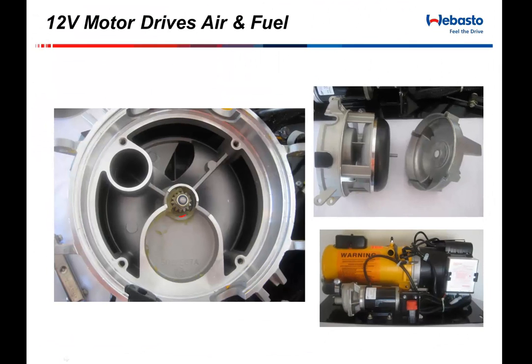On the other end of that shaft is this gear, which again is driving the fuel pump. So it's kind of easy to show that that 12-volt motor is both driving air and driving fuel. Keep in mind that in series with that 12-volt motor is an inertia switch. That inertia switch is put in there so that if something catastrophic happens, like the bus rolls over, that switch pops, and it will discontinue airflow and discontinue fuel flow to the heater, ultimately turning the thing right off.